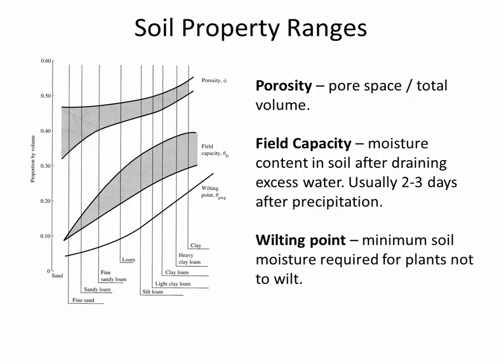And you'll notice that the field capacity is much higher for clay than it is for sand. And so that's right along with what I've already told you, that the clay holds on to the moisture more easily than the sand does. The water passes through the sand very easily, and so its field capacity a couple of days after precipitation may only be 0.1.